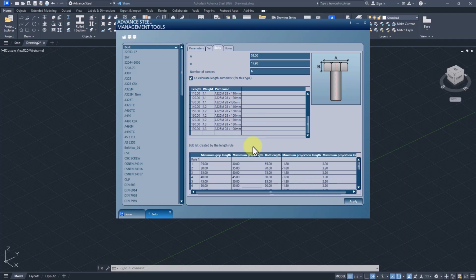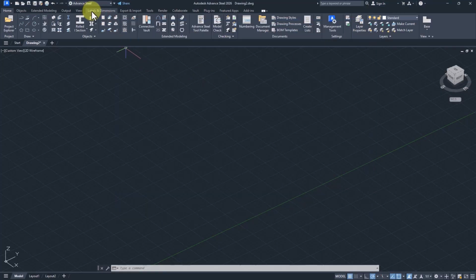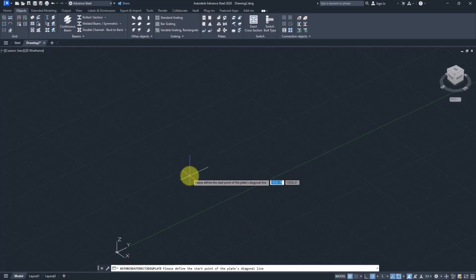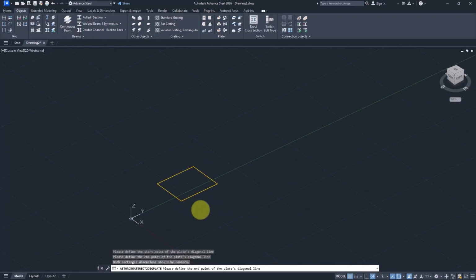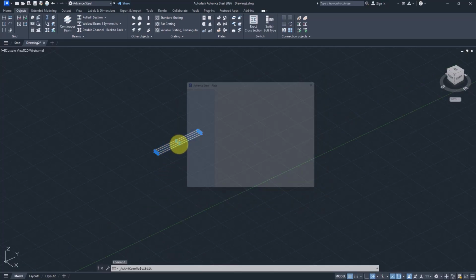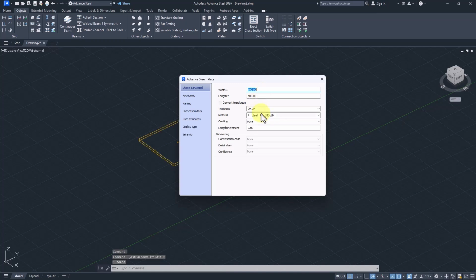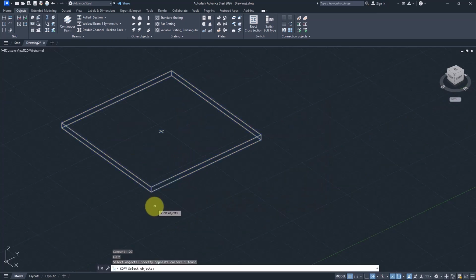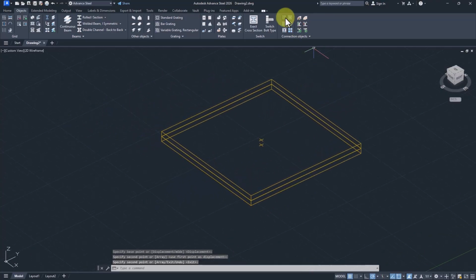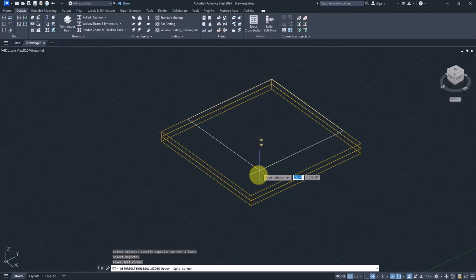Let's apply this. And we can basically do this for any bolt with any specific size that we want. Now let's try doing a little bit of test here. I'm going to go ahead and set this rectangular plate here. For the dimensions, give me 500 by 500. Thickness on 20. Oh, what happened? Oh, 500, sorry. It was 50. I'm going to get a copy of this plate. Now select both, select these two, enter, and set this boundary here.